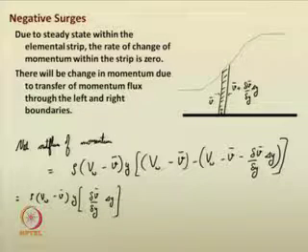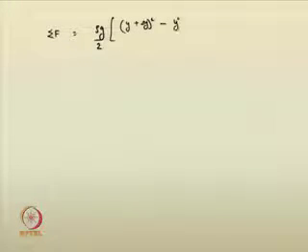So I have simplified it here. This net outflux of momentum is equal to the net force in the system. The net force acting in the system, sigma F, I hope you recall, is rho g times (y plus del y) whole squared minus y squared, by 2.